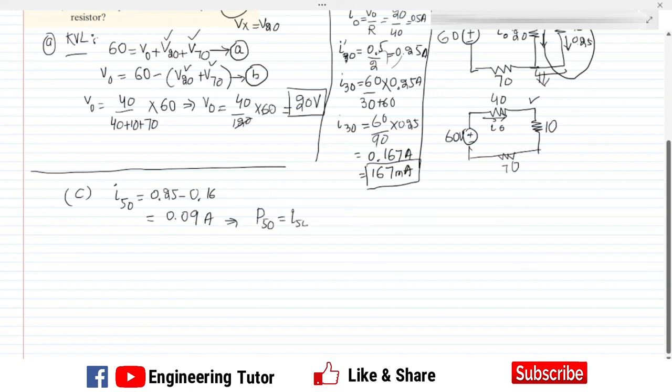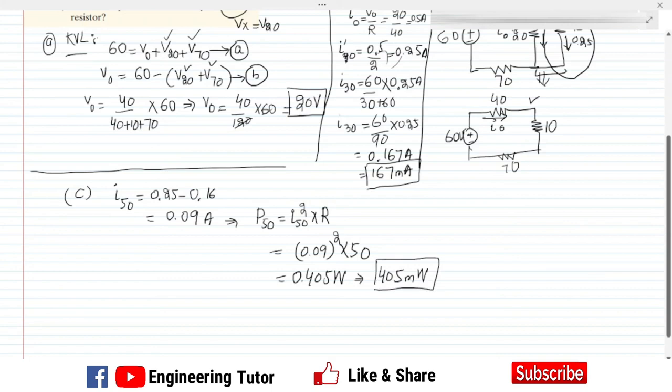Now in order to find the power dissipated by the 50 ohm resistor, we know the formula, which is I50 squared multiplied by R. By putting values here, 0.09 squared multiplied by the resistor, the value here will be equal to 0.405. Let me write it here, 0.405 watt or 405 milliwatt, which is the power consumed by the 50 ohm resistor.